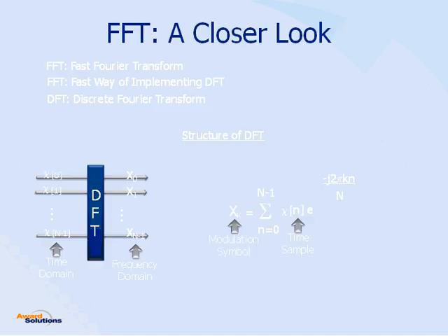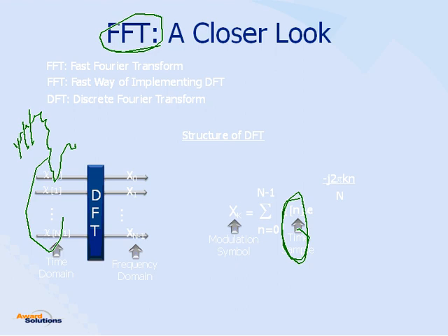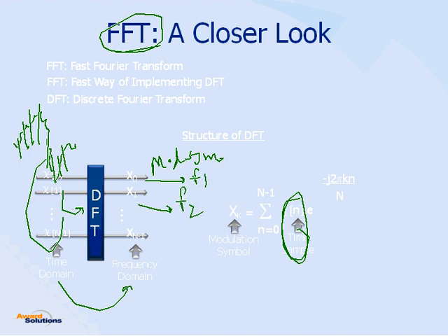That is the idea. And again, FFT here is a mathematical formula. So you take the time samples, the strange looking waveform that I discussed, you take samples. Those samples go into the DFT, and from the time domain, you get your frequency domain. These are your modulation symbols. One modulation symbol on one subcarrier, another one on another, and so on. This is that formula.